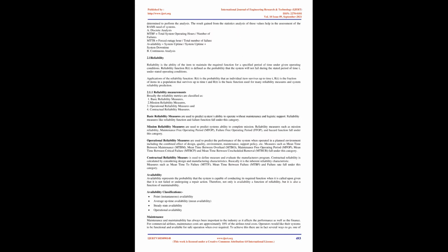The scheduled maintenance of an aircraft contains hundreds of timely/cyclic-based inspections and replacements of parts. These can be divided into about 40, or more, groups with different periodic intervals, which are developed from maintenance strategy like MSG3. Even if a system is maintained, deviations will occur. These deviations must be considered separately since they have a tendency to occur randomly at times, and these are the unscheduled maintenance tasks. All implemented maintenance tasks, scheduled as well as unscheduled, must be recorded and archived.